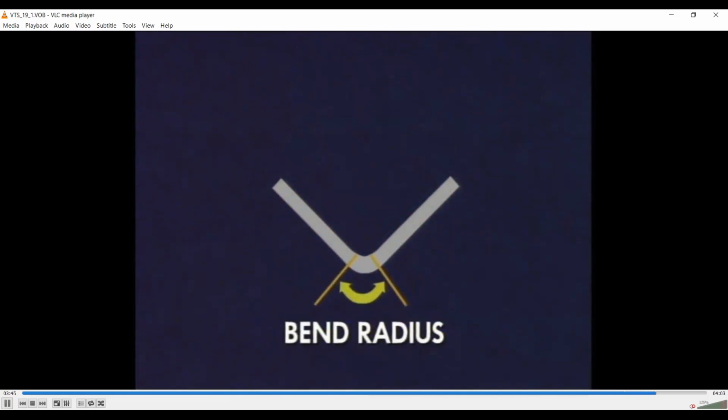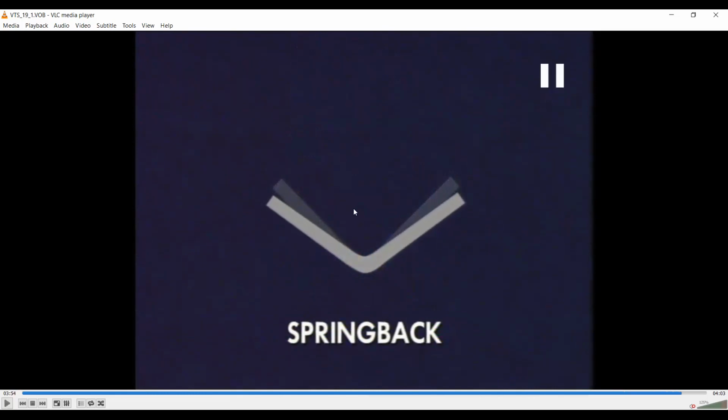And there is the bend radius. So in the calculation that we made, the inner radius was taken to be the bend radius. The spring back is increase in the included angle or decrease in the bend angle. So that should be catered for as well in the case of bending operations. Now we will watch another video where we will see other bending operations like flanging and hemming.